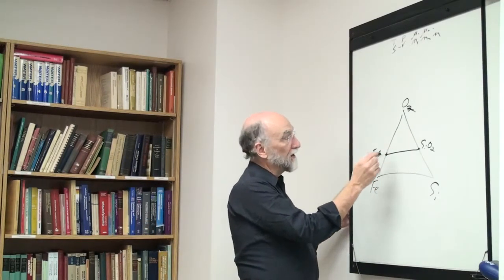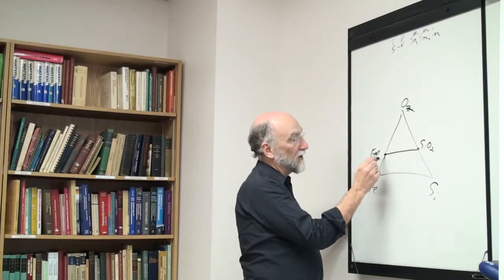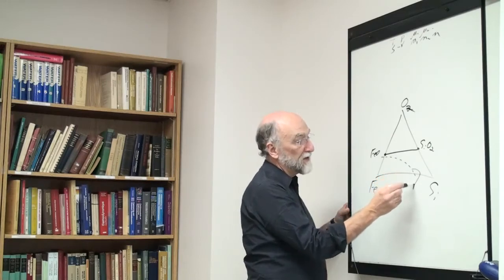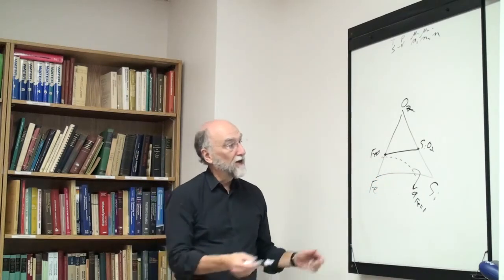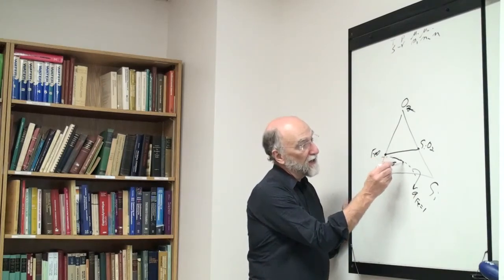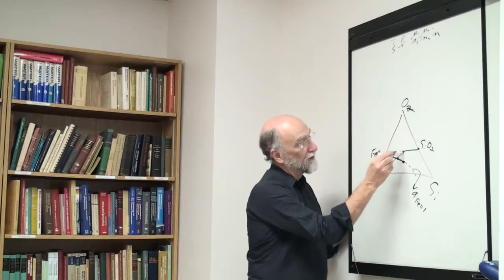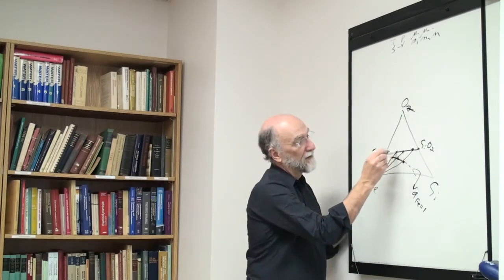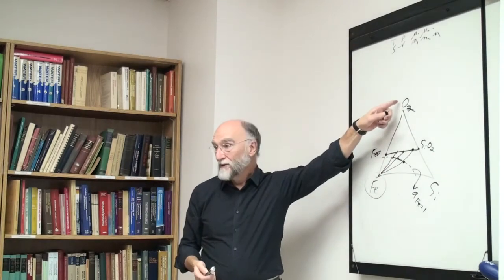Okay, so I'm going along, this is before I went along a line of constant oxygen activity. Now I'd be going along a line of, say, constant iron activity. So this is the activity of iron equals 1. That's the line along when it's in equilibrium with iron. So now I would have tie lines lying along here, and I could project through the iron corner. Same sort of idea, except I'm projecting through this corner now rather than through that corner.